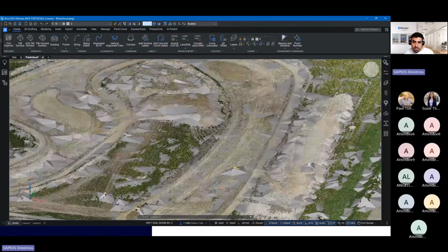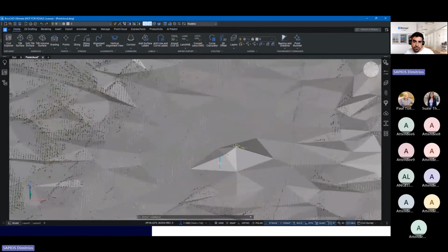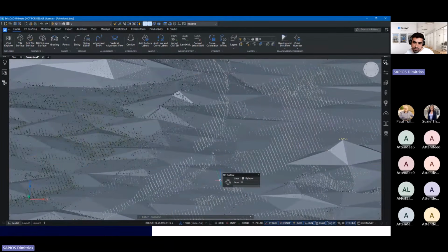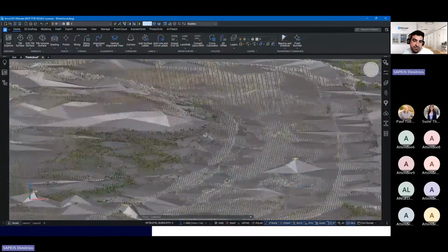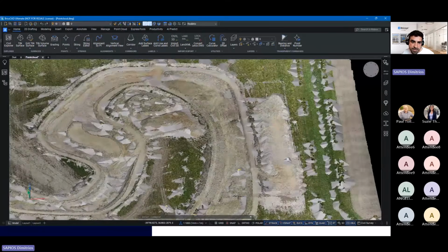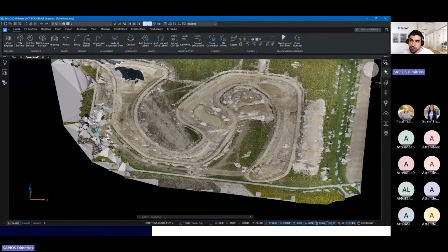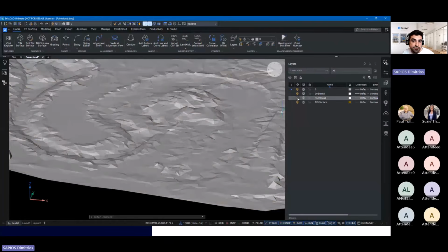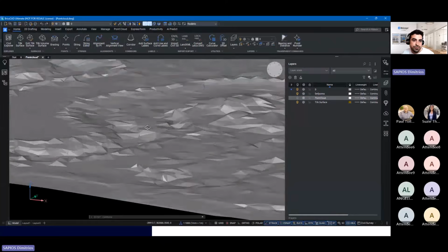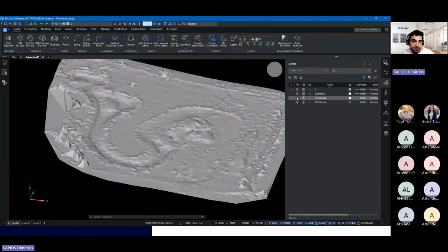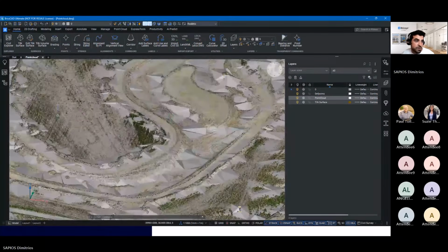As I start zooming in, I notice that the detail of the thin surface is quite low. It ignored many points with each distance or elevation I defined earlier. So in order to fix that, let's first make it a bit more visible by turning on and off the point clouds. We can already see the detail is quite low. So let's fix that, shall we?